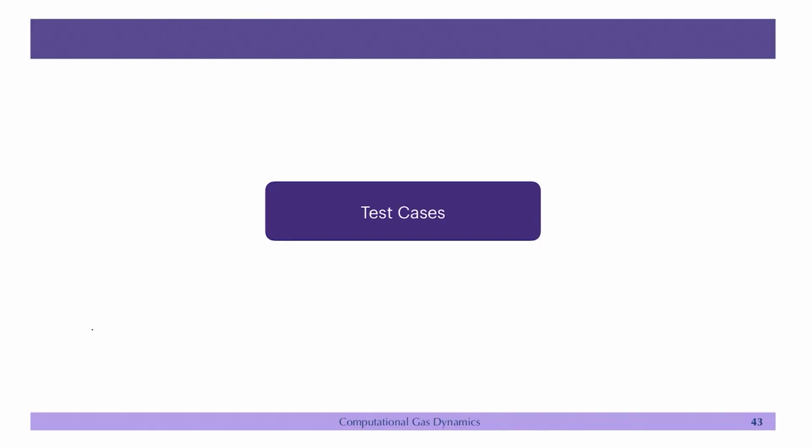So, as we have discussed earlier in CFD, we have 3 steps. One is the pre-processing, where you basically make the grid. First you make the geometry if you have, or you can import the geometry from somewhere, and then you make the computational domain. Then you make a grid in the domain.